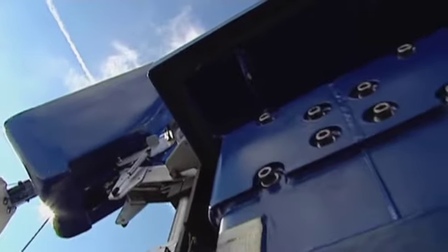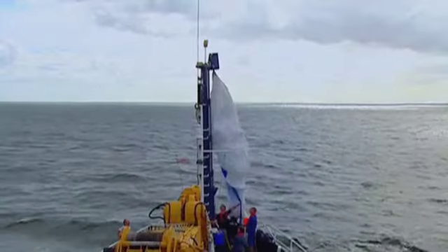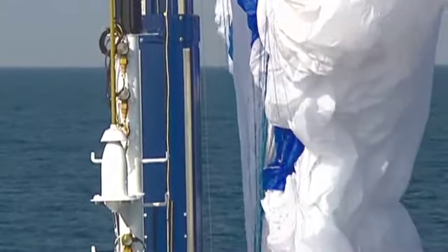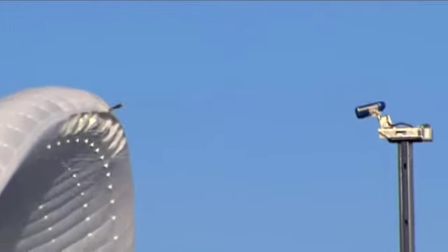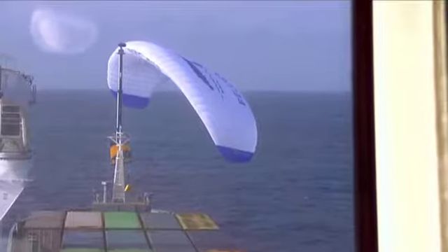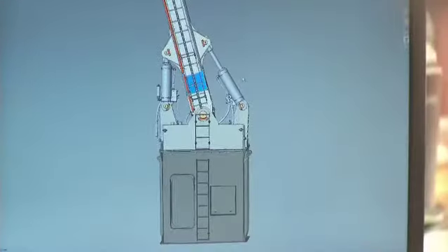My role in the team is to design the telescopic mast, which is part of the launch and recovery system. The ship usually rolls by plus/minus 20 degrees, and it goes up and down by plus/minus 5 meters. The mast length is approximately 25 meters, and you can imagine how much movement we have at the top of the mast. That creates a lot of forces which we have to handle.